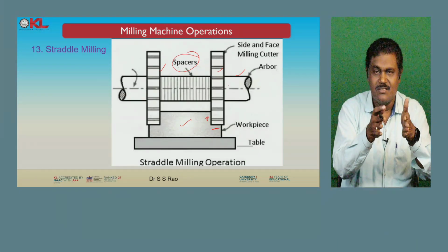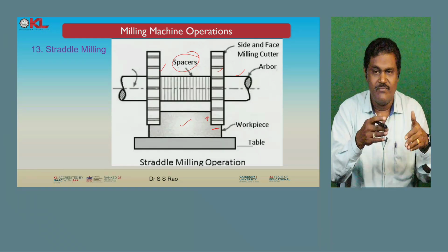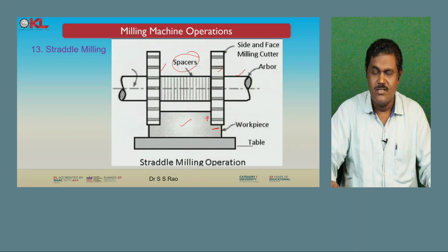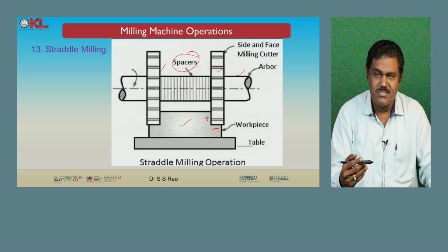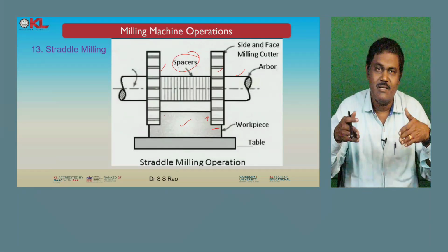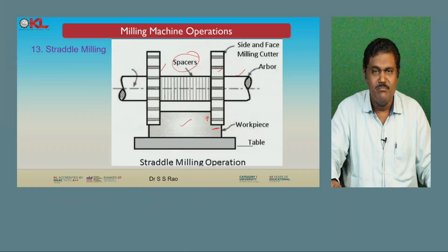Likewise, there is a different set of cutters you can fix, and you can perform the straddle milling operation. So in this, the machining operations on these two sides can be performed simultaneously by using the straddle milling operation.